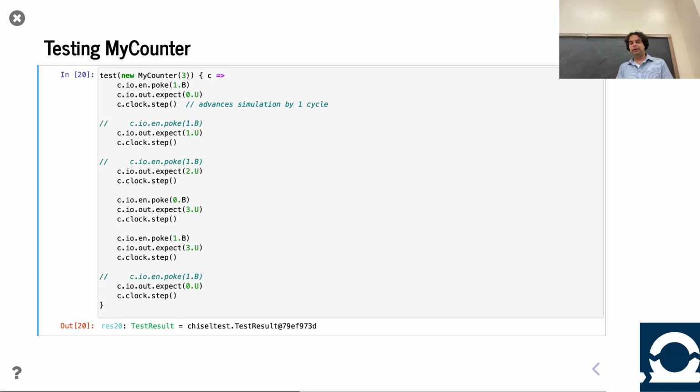Another place Verilog might show this is what if you have a latch rather than a register? Yes, you can do latches in Verilog. Most design houses are very restrictive on when you can use them. In Chisel, they're not built in. If you want to put them inside of a black box, you can, and then simulation is going to be a little wonky. The third time difference in Verilog is that you can put this pound specifier to have an explicit delay. That's a simulation-only construct.